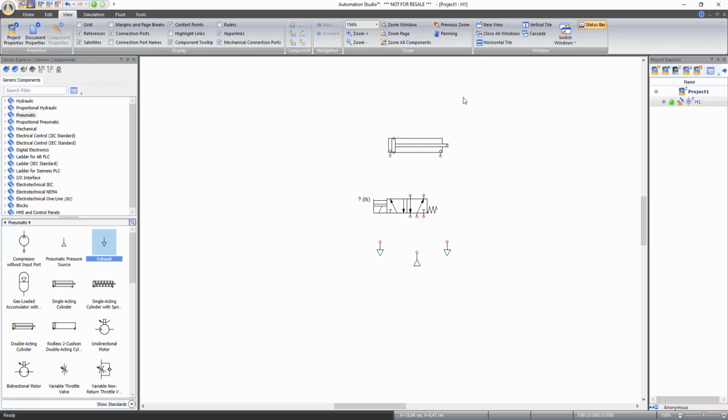To pan the document, click on the panning function of Zoom tools. When you click on the panning function, the cursor transforms into a hand, and then you can pan the document by holding the left mouse click and moving the cursor. Alternatively, you can press and hold down the space bar and move the cursor to pan the document. To disable this function, just right click on the document.